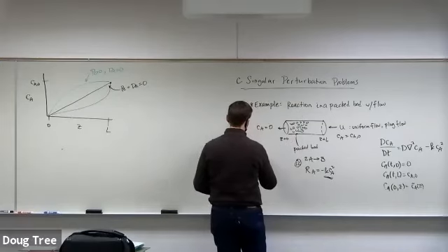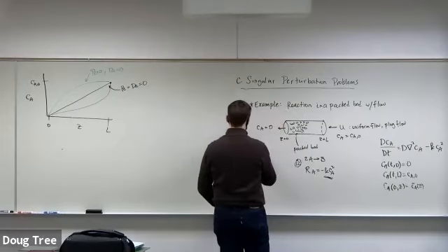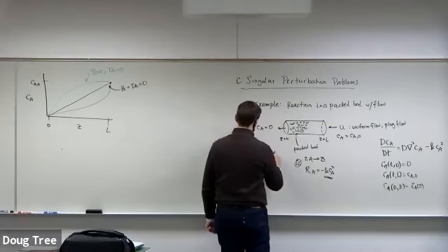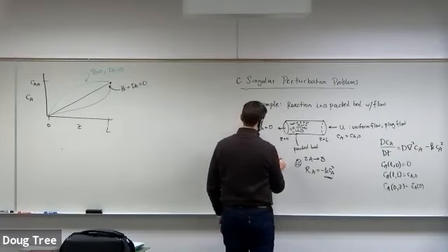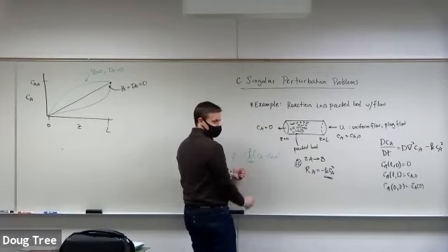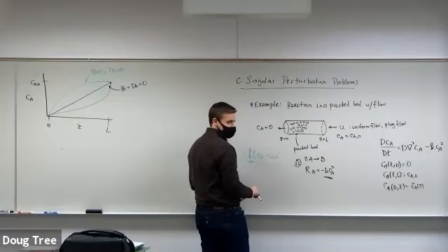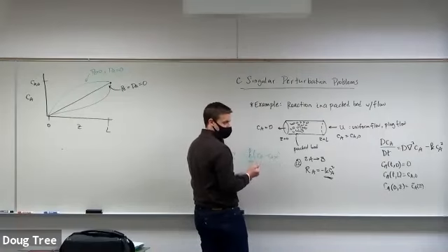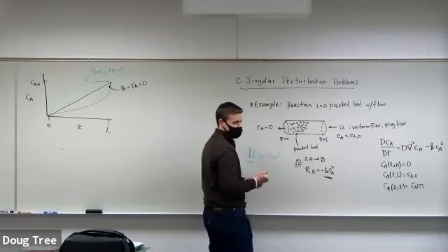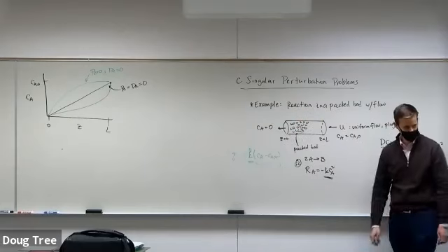So it's like h(T minus T infinity), it's k_c(C_A minus C_A infinity). Right, and that was equal to a flux. And when this number is really, really high, it's essentially making those two things equal to each other. Does that make sense? Just need to think about it. So it's in your diffusion.